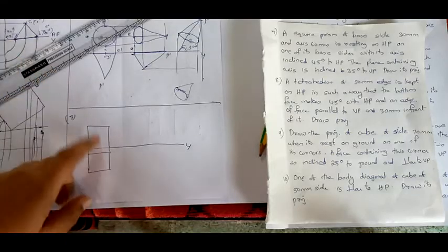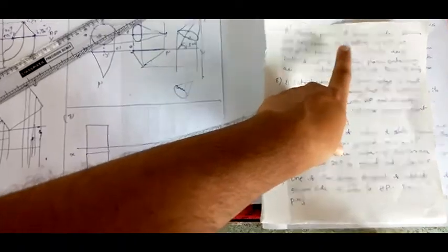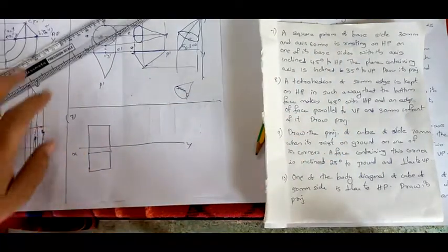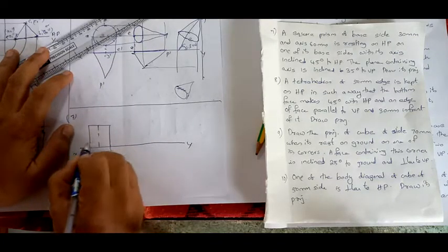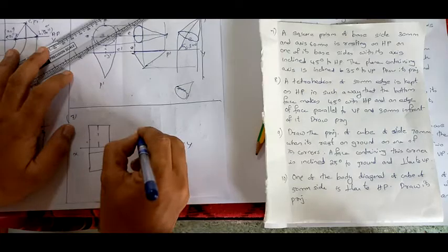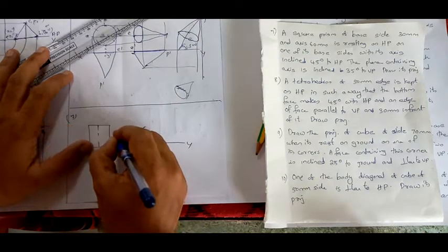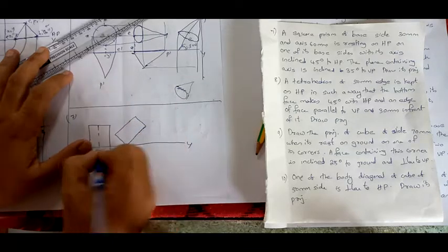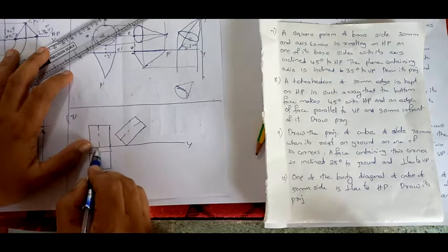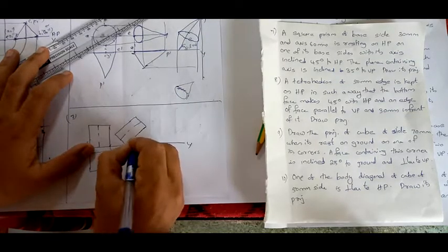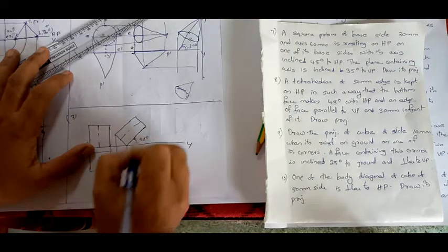For the front view and top view, I have already told that it is resting on one of its base sides, so on the right side there should be the edge. Now you have to give the axis an inclination. In a prism these three edges are parallel, so the axis is inclined 45 degree: draw a line taking the axis at 45 degree and redraw this figure. The advantage here is that if you give inclination to this line, it is the same as the axis. So you give inclination of 45 degree to this, and the axis will already be inclined 45 degree. Now reproduce the figure.